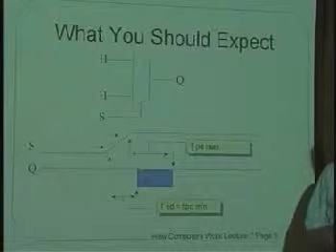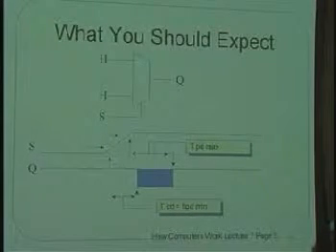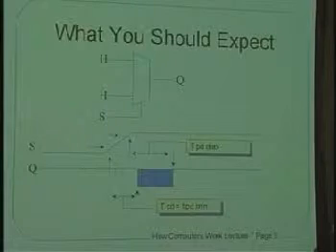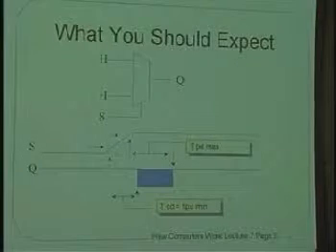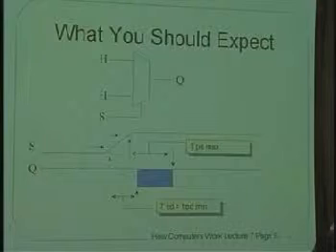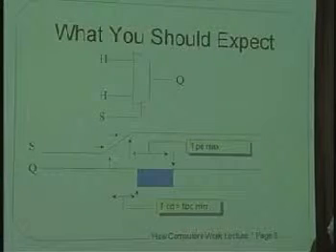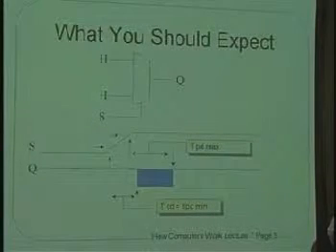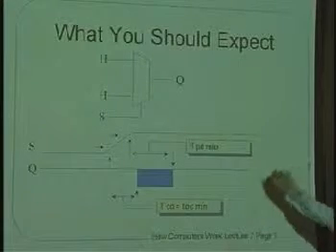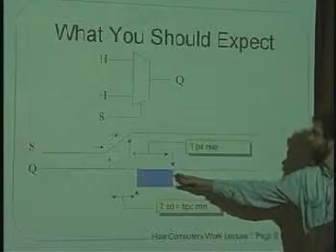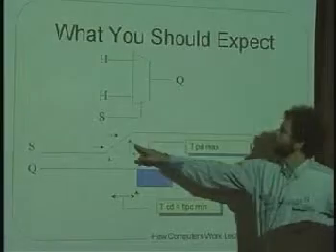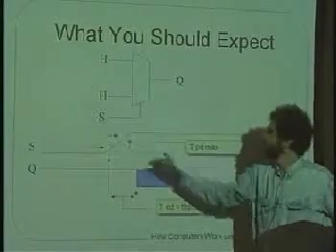Does it sort of make sense? The left side of the blue box has nothing to do with the top of the slope of S. Correct. Only has to do with the beginning of when S begins to go up. That's absolutely right. Move the top of the slope far to the right. Why can't I have TPD max? Because TPD max is measured from the end of the slope. Right. So this whole thing shifts over.